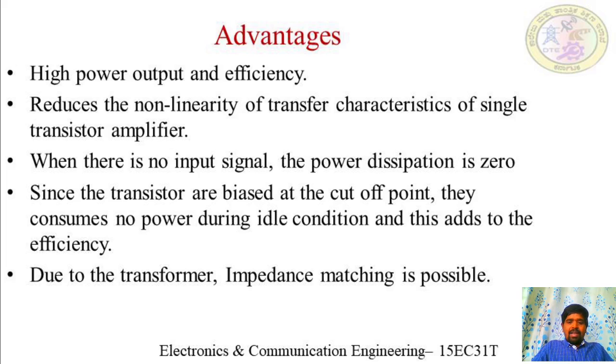And as I already mentioned, a very important point: when there is no input signal, power dissipation is zero, and the transistors are biased at the cutoff point. See, this is a very important point. In a push-pull amplifier, the transistors are biased at the cutoff point, so they consume no power during the idle condition. And the last advantage here is that we are using a transformer at the input side and at the output side of the amplifier, so we can use it for impedance matching also.